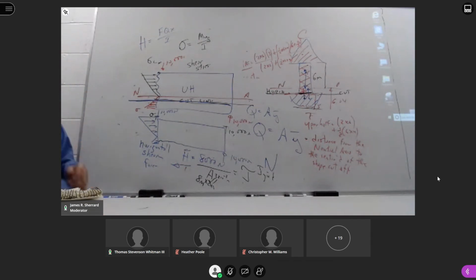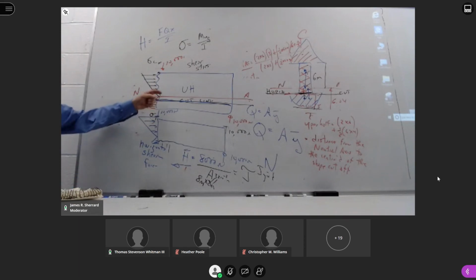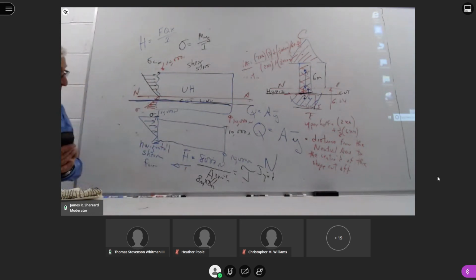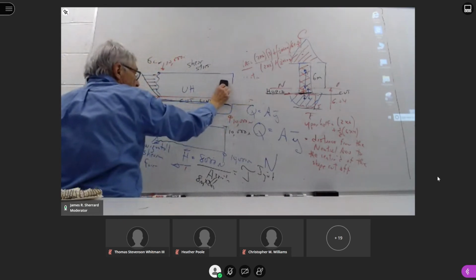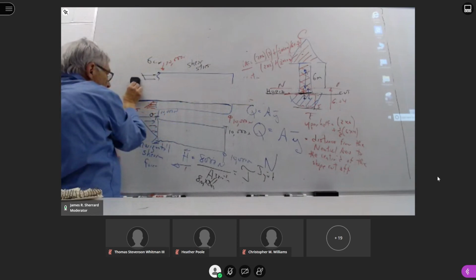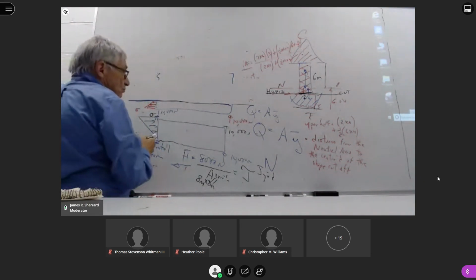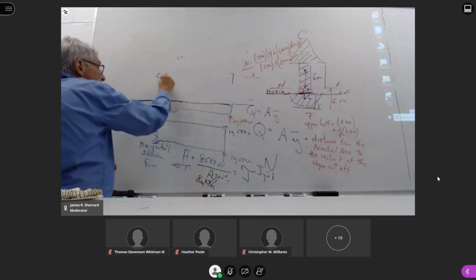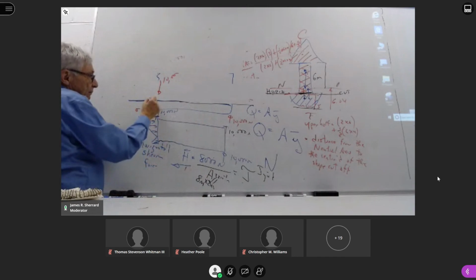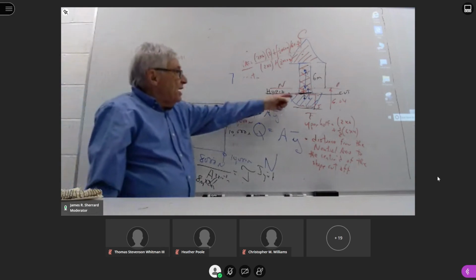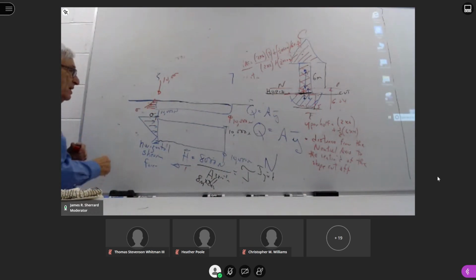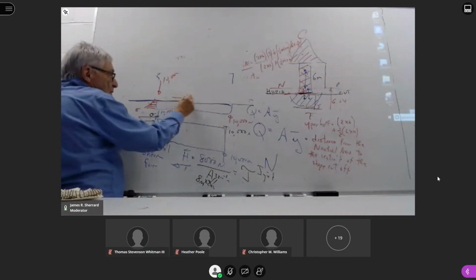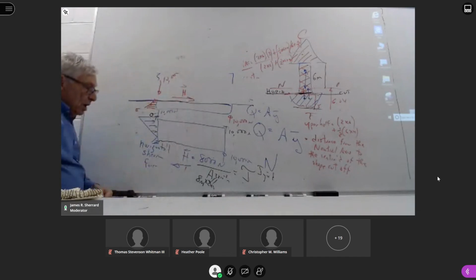Right, but when you just drew the free body diagram for the lower half, in the previous one. Let me go back up and do the lower half, okay, because I don't have the lower up here anymore. So I'm just going to erase this. Okay. So 10,000 is good. Got to put another 10,000 here. And then if that was the cut line, it already has a negative value on that cut line because it's below the neutral axis. So this is going in the direction because it's in tension. Okay. And in this case, it makes it want to go that way. So here we'd have to have the horizontal shear going that direction, so it makes it want to go clockwise. Just like the one down here was primarily that way, they're going to balance one another out.